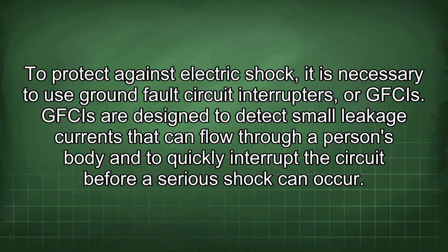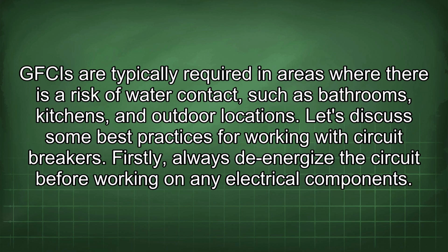GFCIs are designed to detect small leakage currents that can flow through a person's body and to quickly interrupt the circuit before a serious shock can occur. GFCIs are typically required in areas where there is a risk of water contact, such as bathrooms, kitchens, and outdoor locations. Let's discuss some best practices for working with circuit breakers.